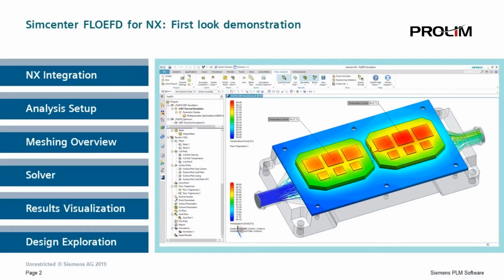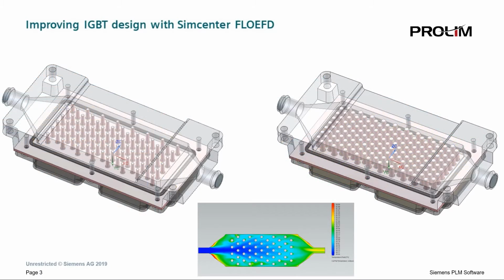By using FLOEFD, we are able to gain important insight into the temperature variation and the flow dynamics of the IGBT module. And we want to see if we can improve the baseplate design to achieve better cooling performance. Thus, a new design was introduced.